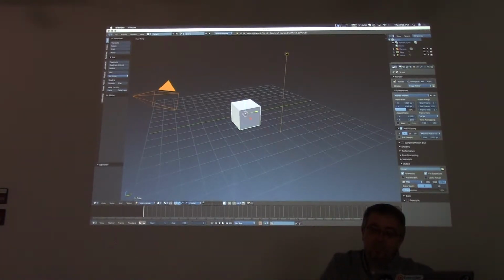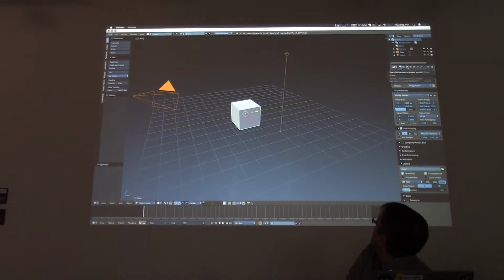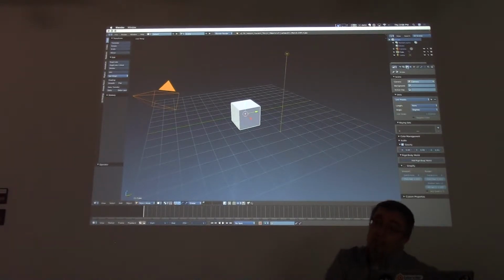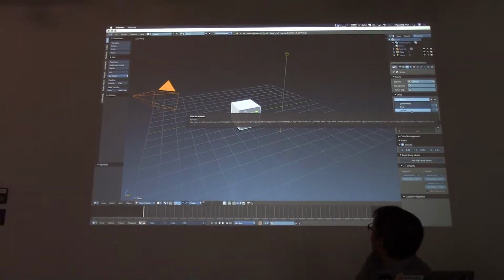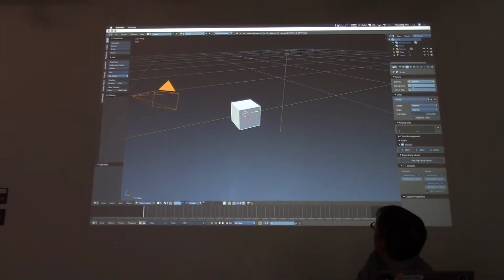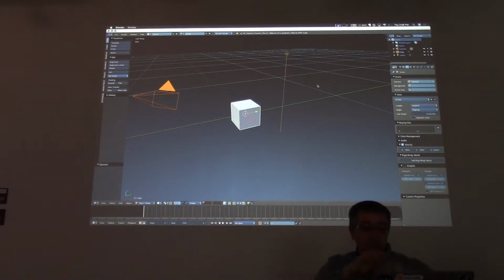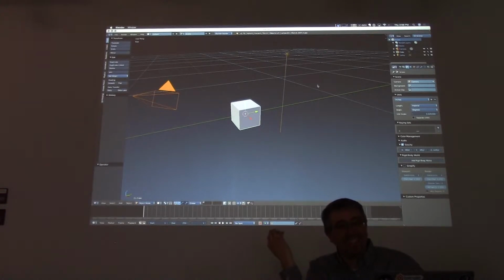So I'm going to go to the Scene tab, which is right here. And these settings are universal across any object that you've selected. I'm going to go down to Unit Presets and click Inches. Okay? So the Scene tab, Unit Presets, and select Inches. That will just set up the scene to operate comfortably in inches. Again, I'll find out tomorrow whether they set up their shot bot in imperial or millimeters. I might have to tell you to switch this over to millimeters tomorrow. We'll find out.